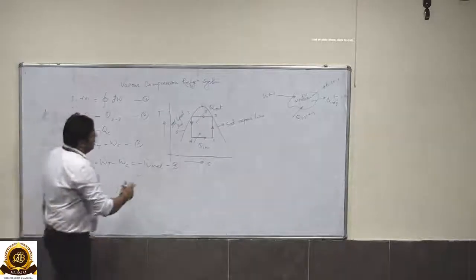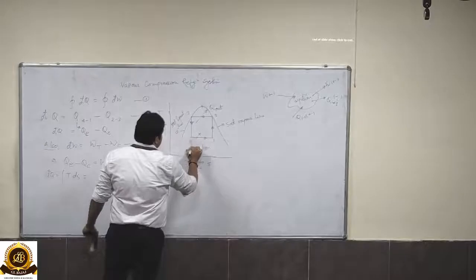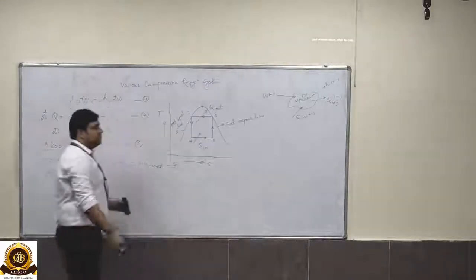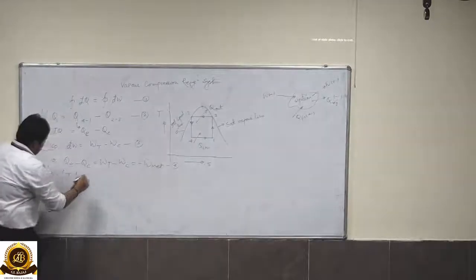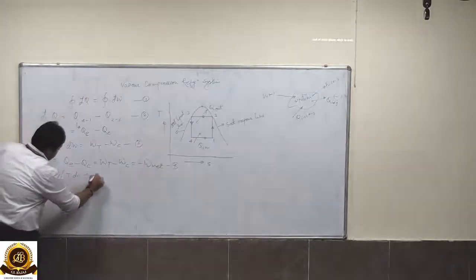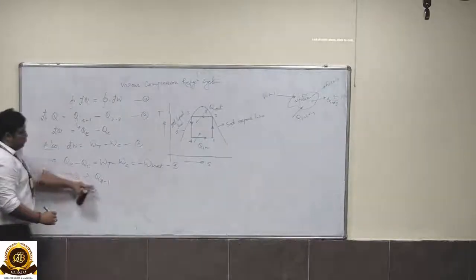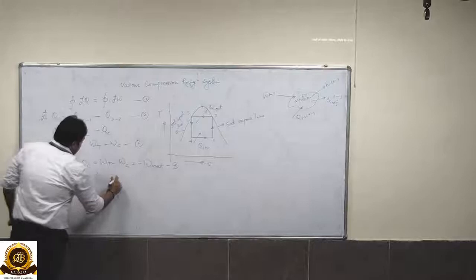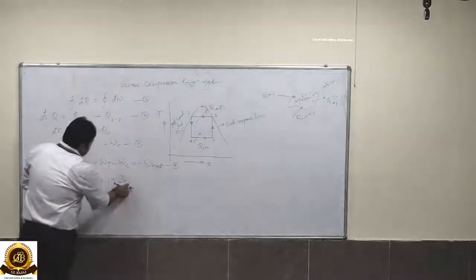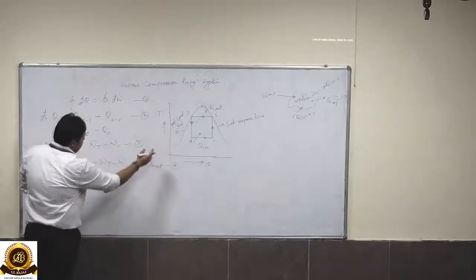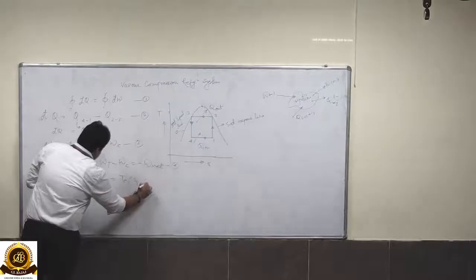The heat is being rejected in process 2 to 3 and heat is being added in the evaporator in process 4 to 1. So if I write Q 4 to 1, which is the QE part where heat is being added, we can represent it by T, the temperature of the evaporator, which is constant here, times S1 minus S4.